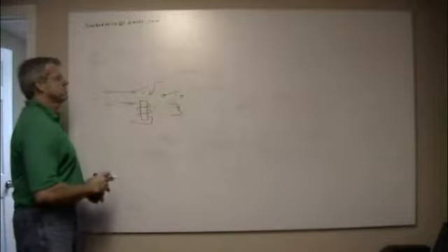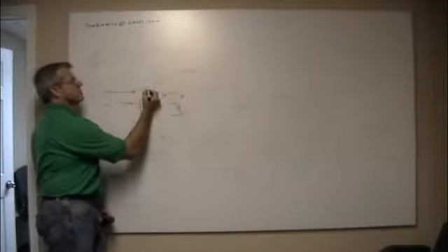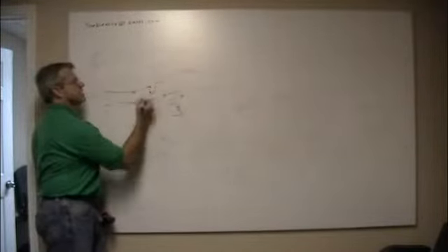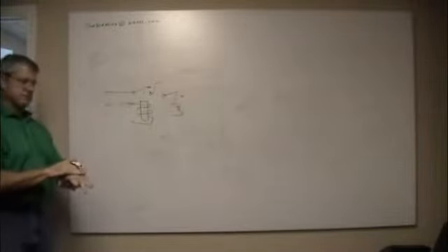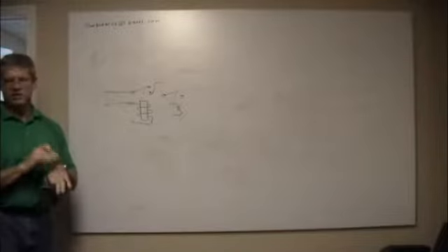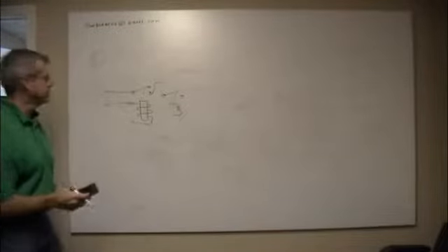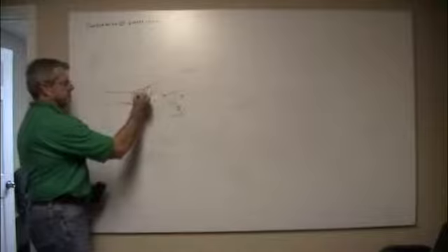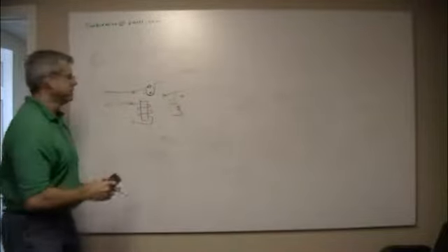Relays, especially when you get into higher powers, their failure mode tends to be this little set of contacts right here. They weld. They come down, they come off. There's a little arc that happens. Eventually they either weld or they get pitted and they don't make good contact and they just quit working. But they always fail right there. Almost always fail right there.